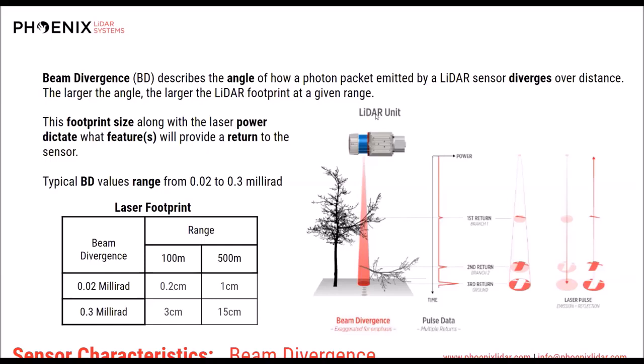Well, I guess what it does show is in mobile mapping, and that's where there's a really important difference in that the minimum range of the LR is 5 meters, and the minimum range of the UAV is 3 meters. So if you have this on a car, we had people put LRs on a car, low on the bed of a pickup truck, and then they wouldn't scan the road just below the scanner because it was just below the minimum distance. So yeah, there's always those gotchas if you want to abuse an LR for mobile mapping.